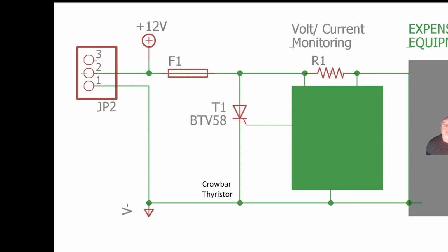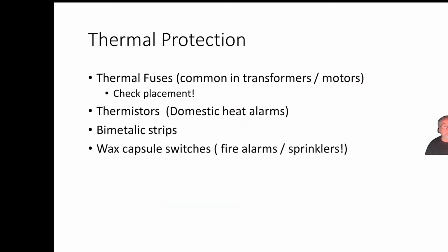It's cheaper to replace a fuse than it is to replace the motherboard or replace this remote monitoring equipment, because it involves some very, very expensive gear or some very rare gear. Much easier to just blow the fuse. And so that's the crowbar. Much cheaper to destroy the fuse than destroy the gear.